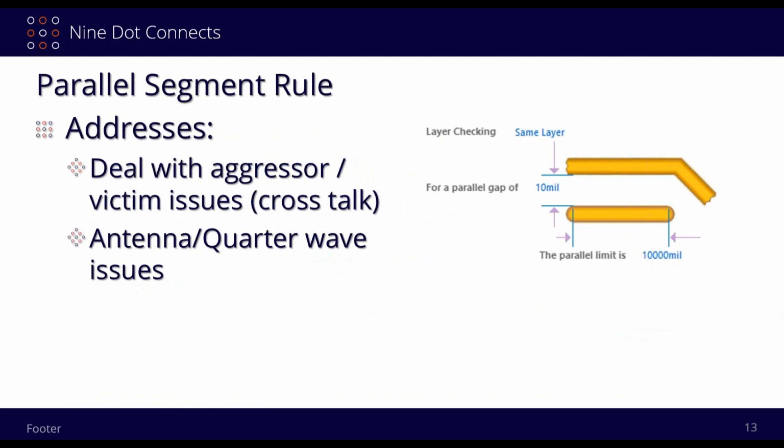This is kind of an interesting area because if you go to the literature on the internet, what I have found more often than not is that people have disregarded this aspect of it. And it shouldn't be disregarded because, as you're going to see, there still can be an opportunity for an antenna even if there's only one signal propagating on that line. And it may not be a consistent signal. I think we always think that this thing is constantly bouncing up and down, and therefore this thing is constantly radiating. But it only takes one signal to basically have a crosstalk event.